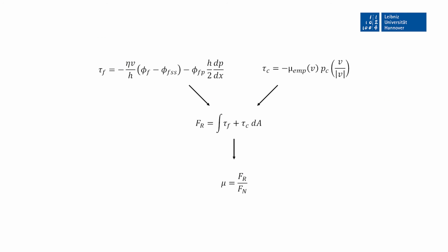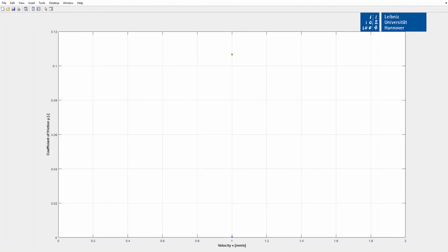In the final step, the friction coefficient in the dynamic seal contact is determined with the help of the previously calculated fluid and contact pressure, as well as the fluid film height, h. The decisive output parameter of the model is the coefficient of friction, which is determined as a function of the operating conditions and the surface texture. The resulting friction coefficients are further processed in the reduced order model of our holistic design software.